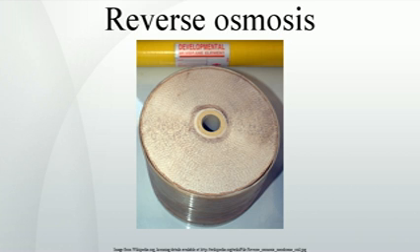Portable reverse osmosis water processors are sold for personal water purification in various locations. To work effectively, the water feeding to these units should be under some pressure, 40 pounds per square inch, 280 kilopascals, or greater as the norm. Portable reverse osmosis water processors can be used by people who live in rural areas without clean water, far away from the city's water pipes. Rural people filter river or ocean water themselves, as the device is easy to use.